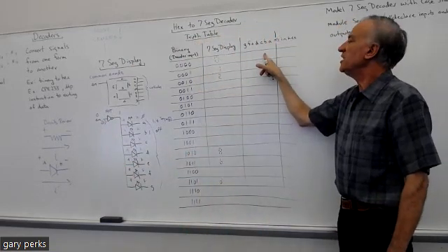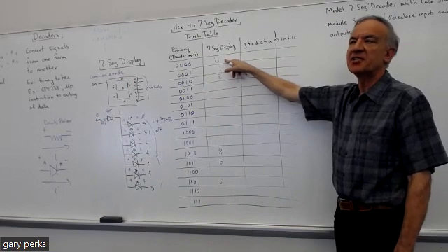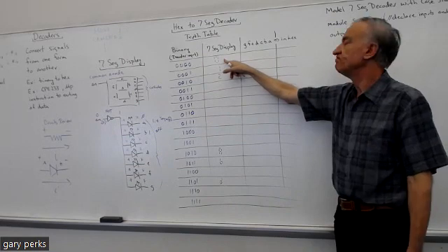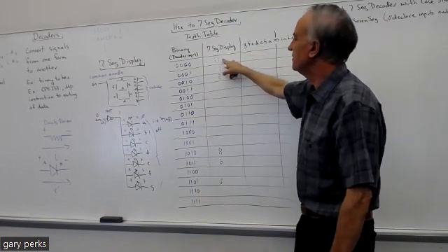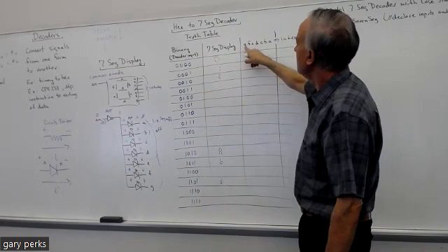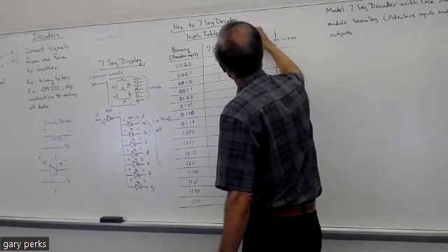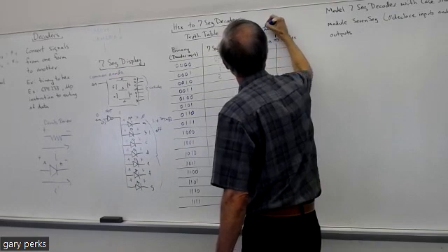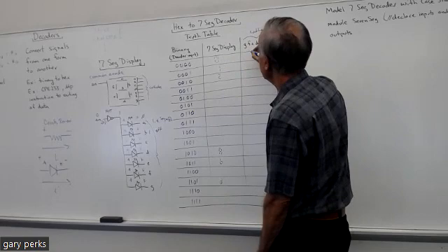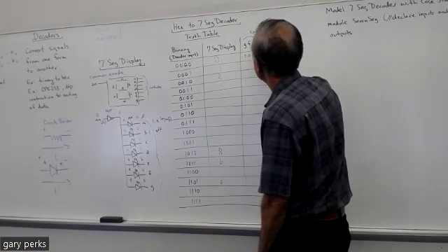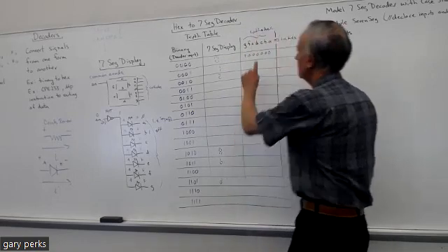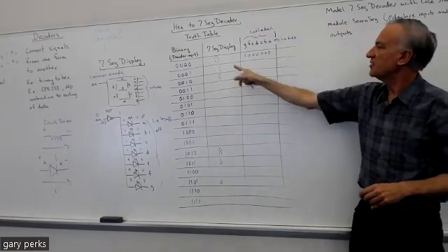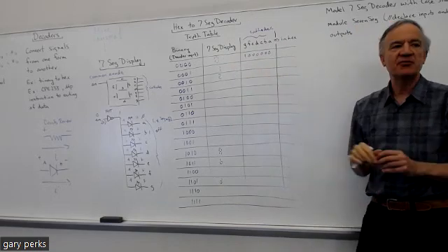So what do we have to make the cathodes of the segments that we want lit equal to? 0. So what would I write here to get a 0 to show up? And see, this is the G, these are cathodes. Does everybody see? It would be 1 and then 6 zeros, right? Because I want all these segments to light. I want A, B, C, D, E, F. I want all those to light. The only one I don't want to light is G. So I make that one a 1, right?